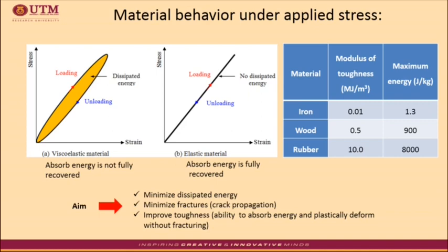The same observation can also be clearly seen as the rubber content increased from 2% to 3%. This proves that the rubber particles may retard the process of crack propagation due to their ability to largely resist stress imposed by repetitive loading under fatigue. The above-mentioned fact is possible as rubber could help to reduce the dissipated energy as a result of the hysteresis effect, as shown in the figure.